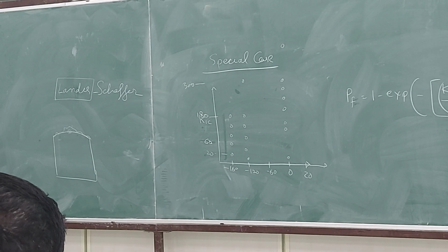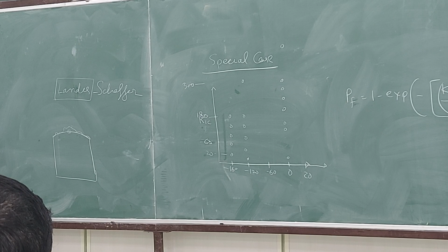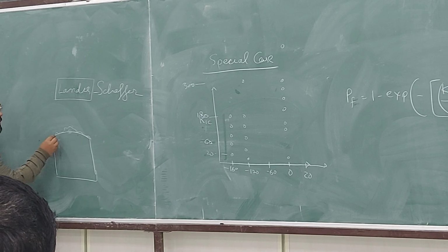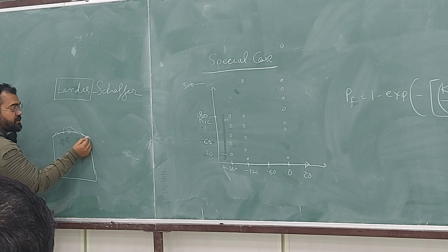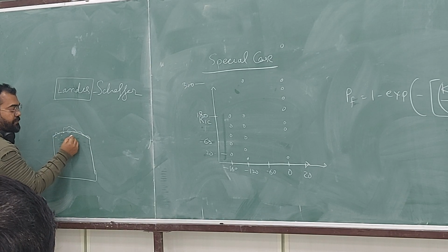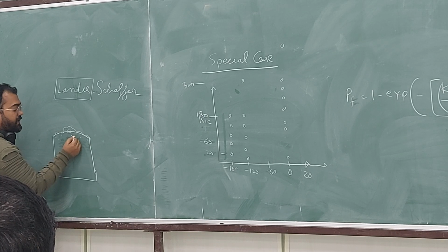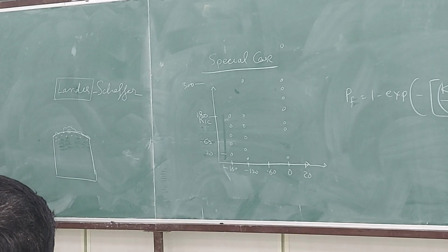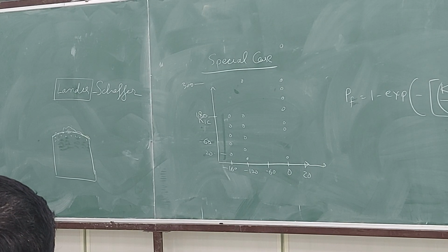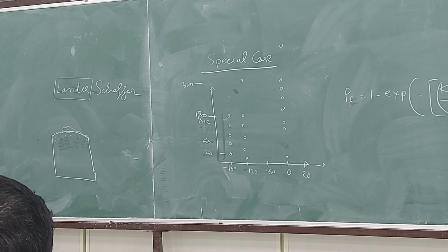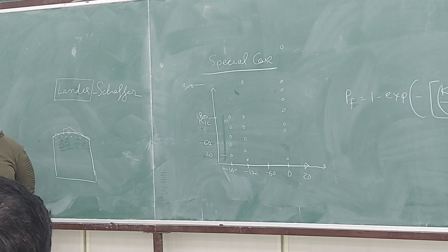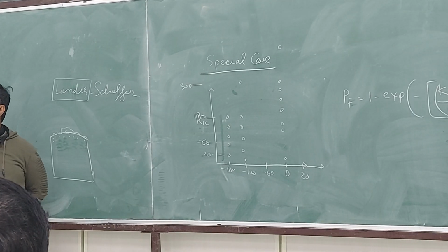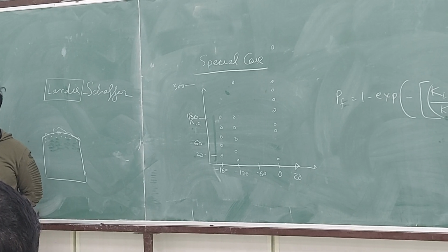Right? This trigger point, this amount of critical K1C, will differ if you have things which can increase the stresses because of their presence, and those things can be carbides, can be inclusions. In ferritic steels you will have carbides, a lot of them. You will have a lot of inclusions. They are oxides, so they don't have that much ductility. So if a stress is applied, they break. Once they break, there is no void formation. There is a separation. Continuum has been broken.